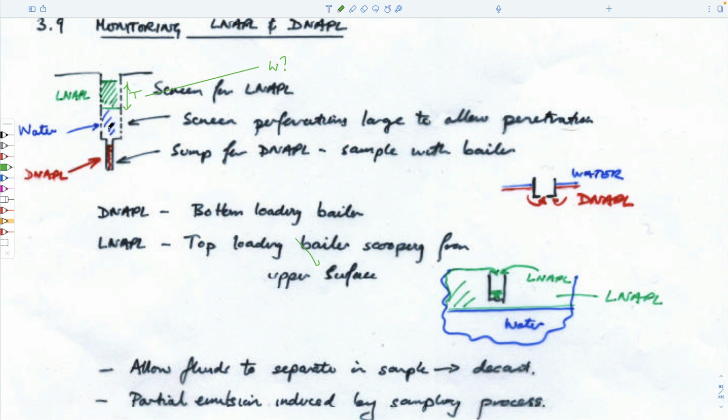And so if we drill a borehole through a gasoline contaminated site, we'd sample this height and we'd measure T, but we want to convert for what the real depth is. And if we know what that real depth is, we can convert it into a mass that's present in situ from the calculation we just did.